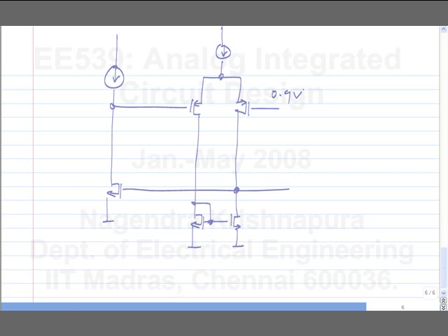So there are two separate things here. Firstly, the effect of random mismatch. The other is systematic mismatch. Even if you design this, in absence of mismatch, what is the quiescent output voltage of this op-amp, the auxiliary op-amp? It is equal to the VGS at this point, right? So you still make sure that the current density in this and the current density in this are the same, so that you avoid all systematic mismatch altogether.